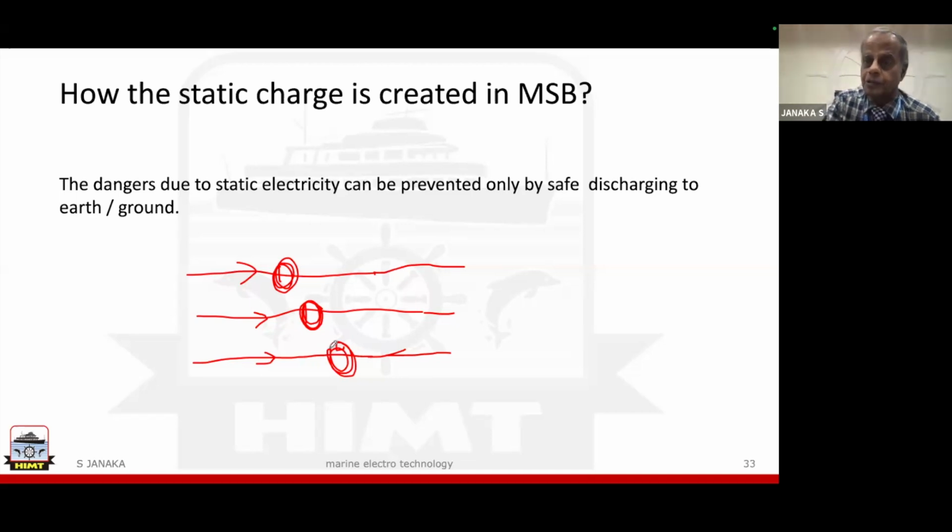The attraction and repulsion of these magnetic fields depends upon the frequency of the supply. The bus bars literally attract and repel, attract and repel. We can't see it, as the frequency is quite high. So the space in between the bus bars is getting statically charged. Even though the circuit breaker is off and the voltage shows zero, the static charges are still there. It may affect the person who is going to work.